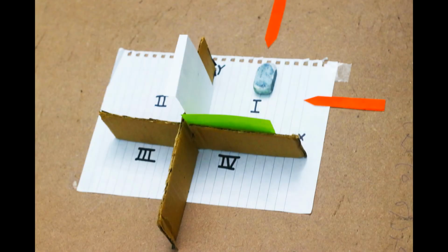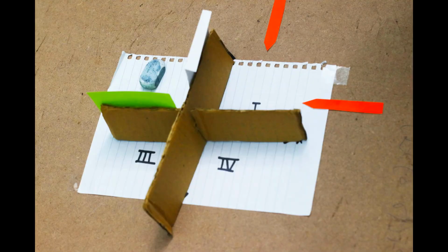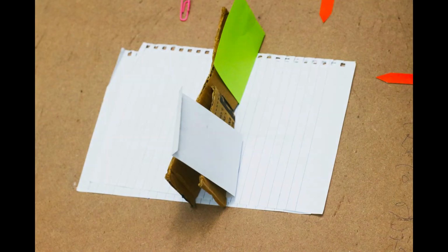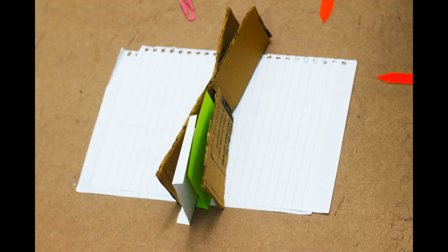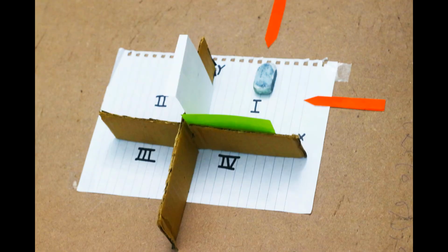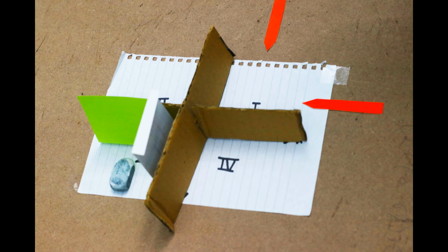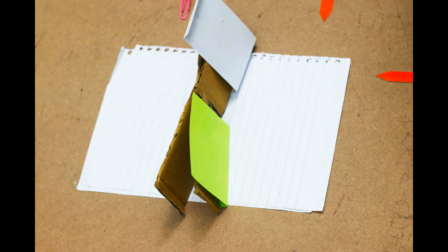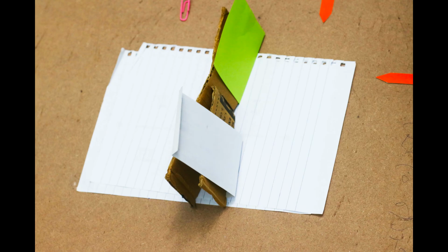After conversion to 2D, when we view objects which had been placed in different quadrants, we can see that the projections of the objects in quadrants 2 and 4 are not usable, as both the front view and the top view coincide in these quadrants. The objects which had been placed in the first as well as the third quadrant result in usable projections. Objects which had been placed in the first quadrant result in something known as the first angle projection. Objects which had been placed in the third quadrant result in third angle projection.